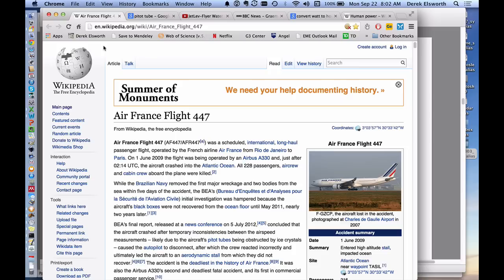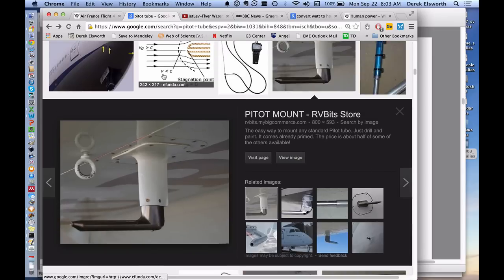An Airbus 330, which is kind of like a 777. And apparently, after the fact, it became apparent that it flew through a thunderstorm. And when the black boxes were ultimately recovered, probably a year or two later, in very deep water off the east coast of Brazil, it had gone through some random moves, gaining altitude, losing altitude. It turned out that the reason for the problem was that the Pitot tubes had potentially iced up in the very cold atmosphere inside the thunderstorm which it flew through.